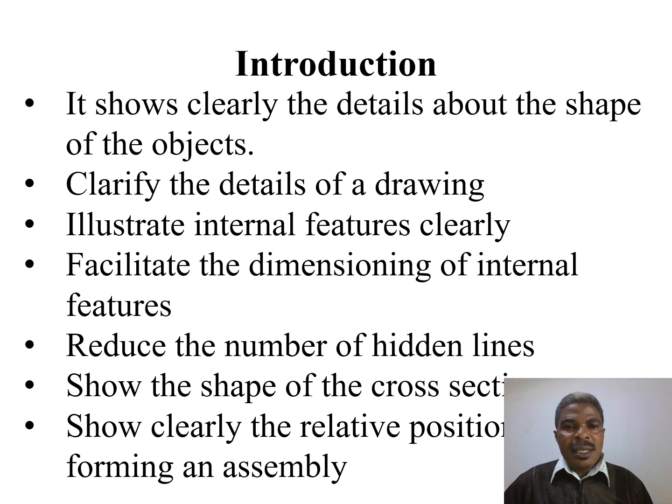And these sectional views are a continuation of orthographic projection and isometric projection. Now for sectional views, we want to clarify the details of a drawing, to illustrate internal features very clearly, and also to facilitate the dimensioning of the internal features. It also reduces the number of hidden lines.